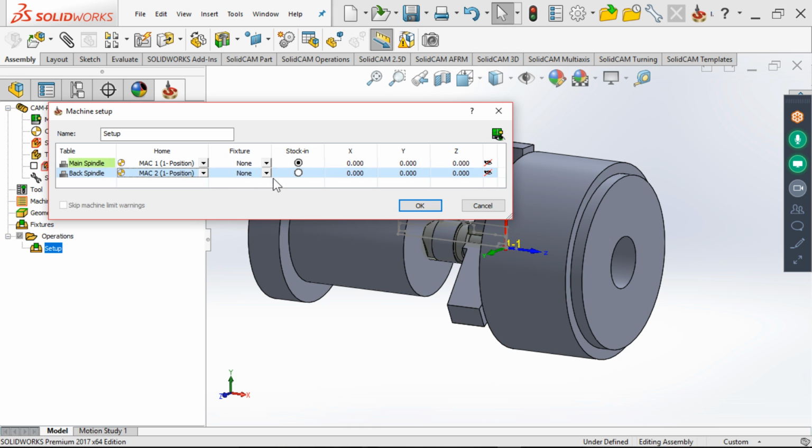Now the fixtures. Let's define some fixtures. Because we don't have it, by default, SolidCAM will generate an automatic fixture. I turn that off just because of these reasons. Just keep in mind these settings because in front of the customer, sometimes you don't want to look stupid.